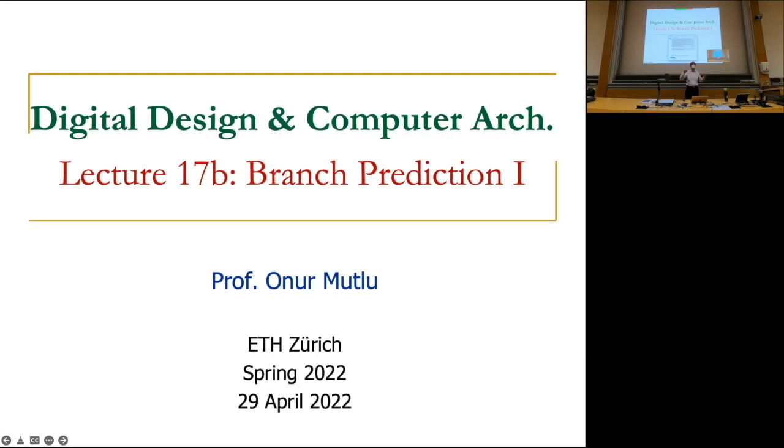Actually, maybe after the branch prediction lecture. It may be actually next Friday, assuming we actually finish the branch prediction by that time. Basically, yes, this is called very long instruction word architectures, and the idea is that the compiler specifies all the dependencies, the compiler knows the structure of the pipeline, it schedules all the instructions, and hardware does nothing. So all of this complexity goes away, and you can exploit the benefits of the compiler, you can dynamically recompile, etc. So this is actually a good idea to explore, but unfortunately, it doesn't work in all cases because it's very difficult to extract that sort of parallelism at the compiler.